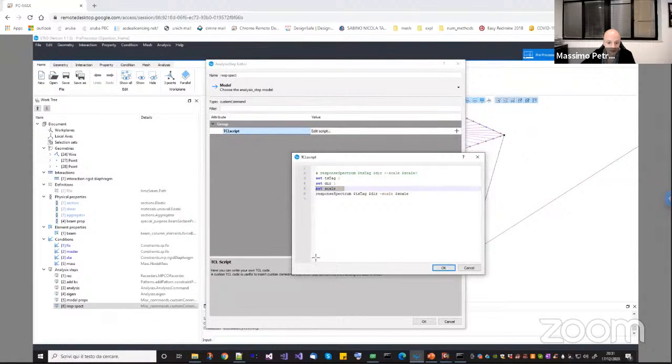Okay, here. So X and Y. And this is the behavior of my structure in nonlinear, with a nonlinear displacement. Of course I don't know it, but at the beginning I compute the initial stiffness and do the eigenvalues. From this eigenvalue, my response spectrum will compute a certain displacement, which is, let's say, here. So this one will be my modal displacement using the assumption of the initial stiffness, which is this one.